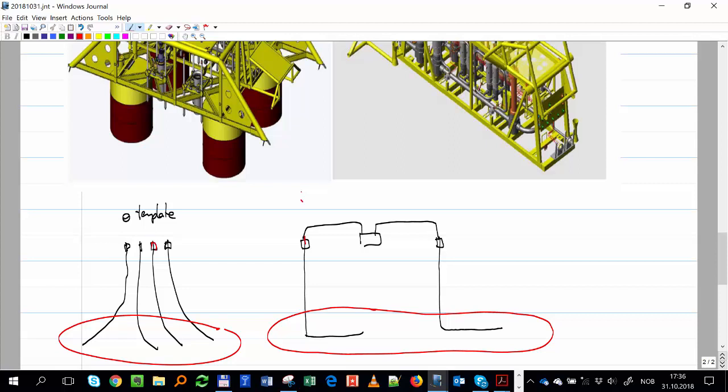What's the advantage of the first one in terms of production? It's not really. It's much better if you make the well as less complicated as possible. Okay, so is this one better in terms of production really? This will be a bit longer, and it will be more deviated, so you have a bit more issues with the pressure drop. Okay, but really sometimes there is not much difference between them. Okay, but this will be longer, so the TPR will be slightly more abrupt.